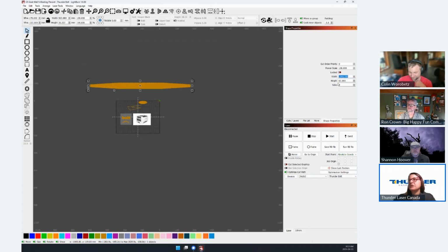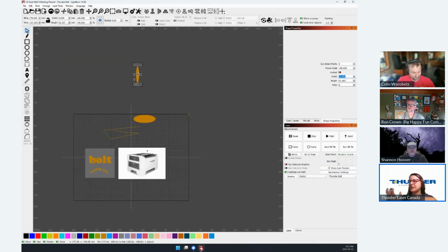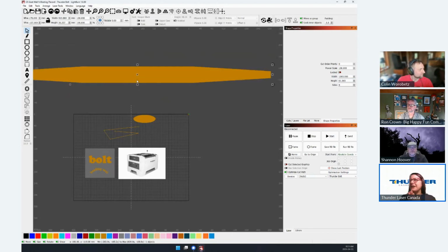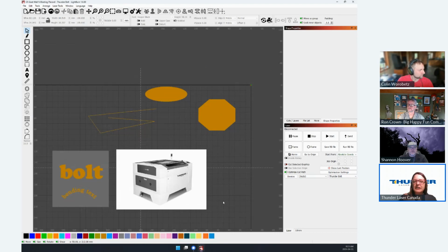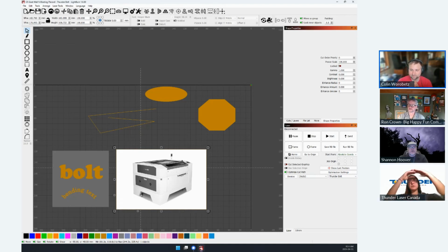That's great. As a new person, I'm glad I have new-person eyes, because some of you are using it all day, every day. One of the first things I learned is that if you're going to cut something out, that should be the last thing you do rather than the first, because if you engrave after you cut, it drops the piece down and then it goes out of focus.